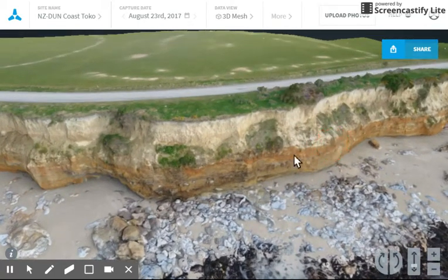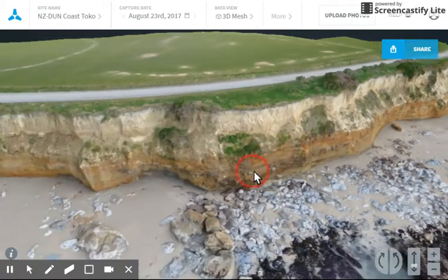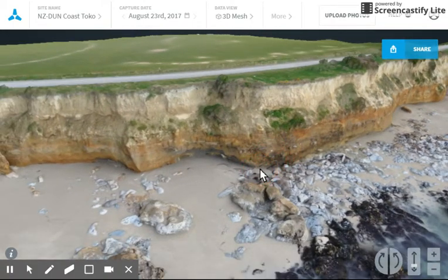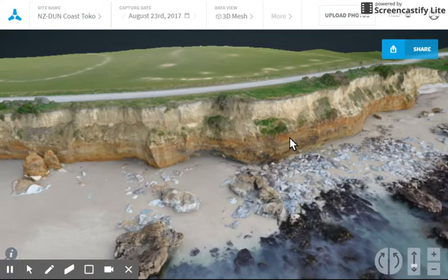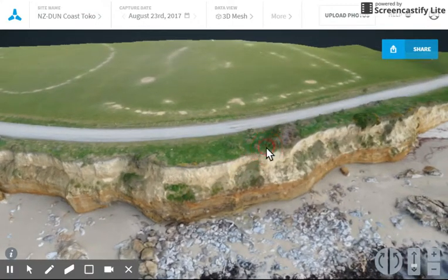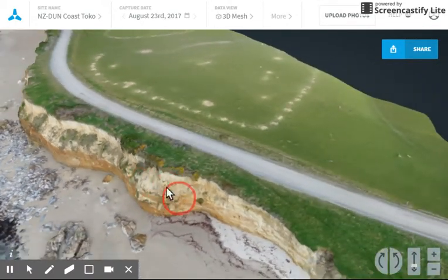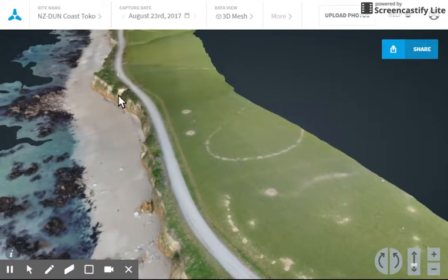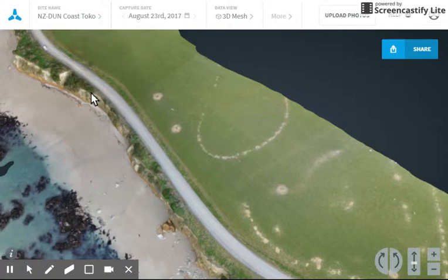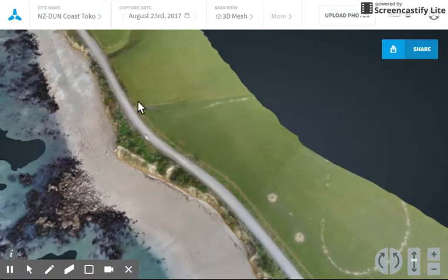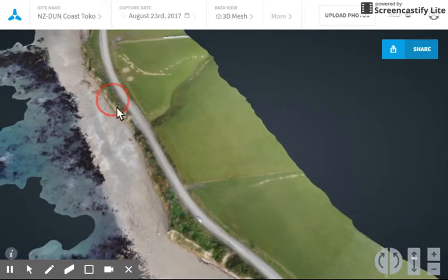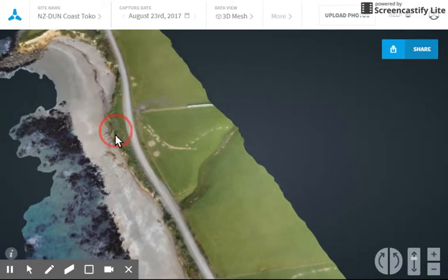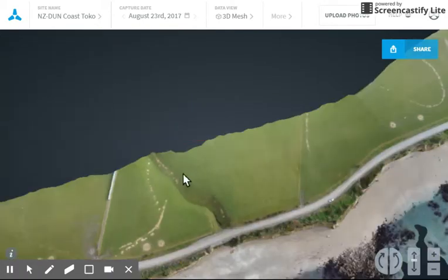We flew at approximately 50 meters altitude and had approximately a 20-degree tilt off vertical for the camera to allow us to be able to see some of these vertical faces with some clarity. We can just do top-down photography, but we find that this particular isometric photography produces a much better result on the vertical information that we're looking to try and gather.